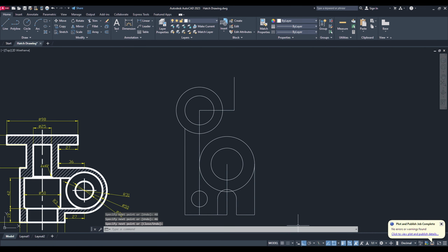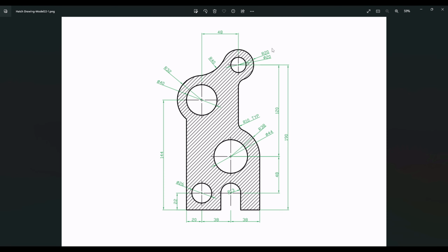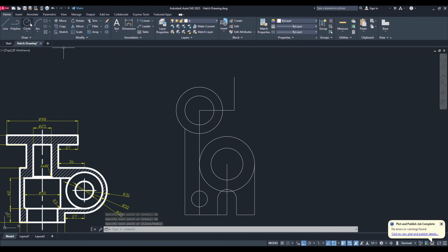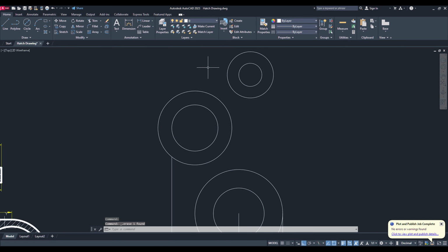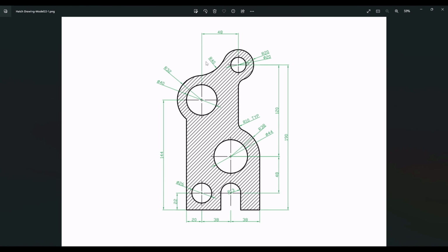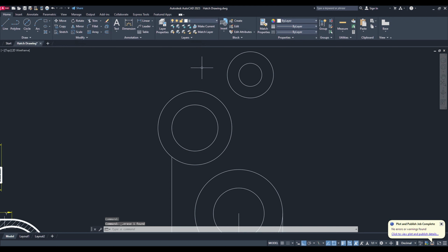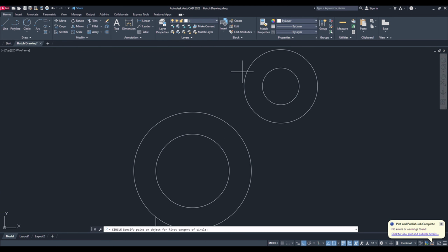And at this point I have another two circles R20 and 20 dia. So to create it, go to center radius and first create the R20 circle. After that, take center diameter and create a circle of 20 diameter. Now simply delete these lines like this. And here I have a fillet. As I can see here, the value of the fillet is R40. So to get it, go to circle TTR and simply click over these two circles and provide the radius value 40, enter.